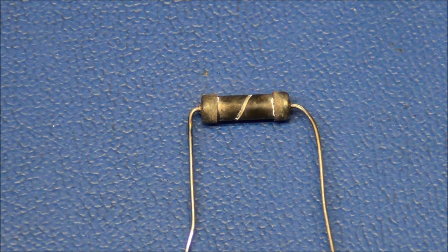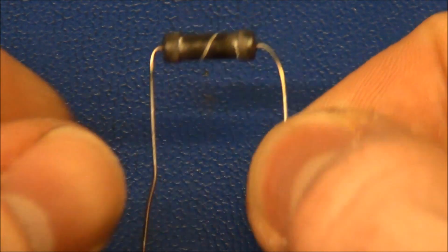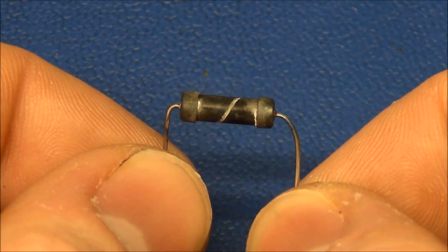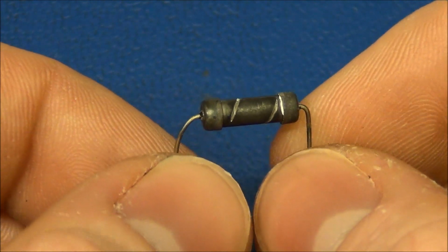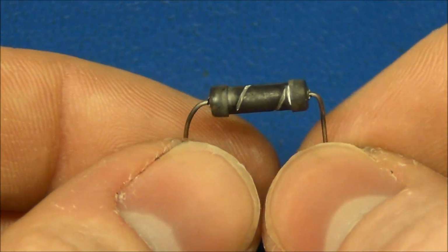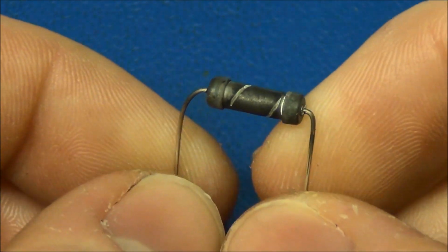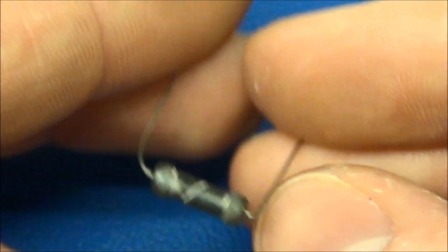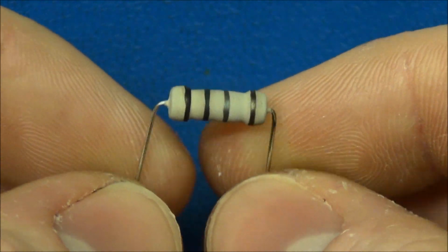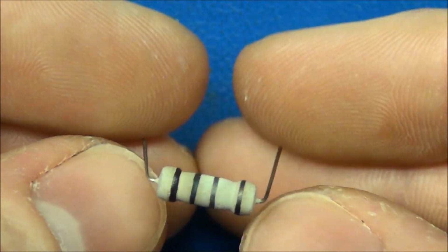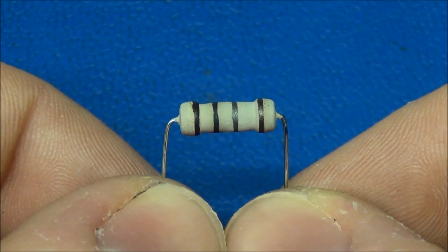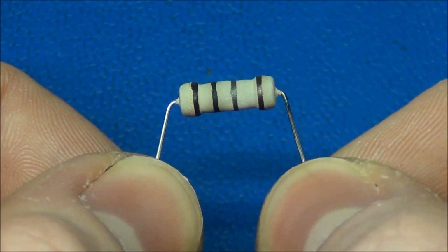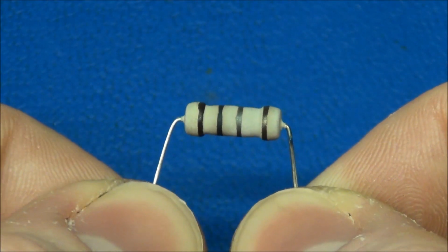So that wasn't actually just for the opportunity to destroy something, because it was two different types of resistors. This one, the first one, was a metal film resistor, the one that started glowing and almost caught fire. And now that it's cooled down, we can actually see the metal film inside. And the other one here is a carbon resistor. This is a 1 ohm instead of a 10 ohm, but I just turned down the voltage until it got to dissipate 10 watts as the other one.